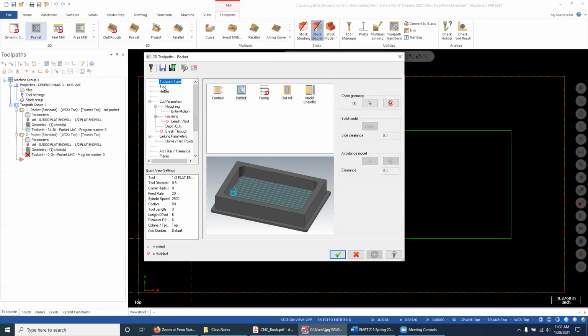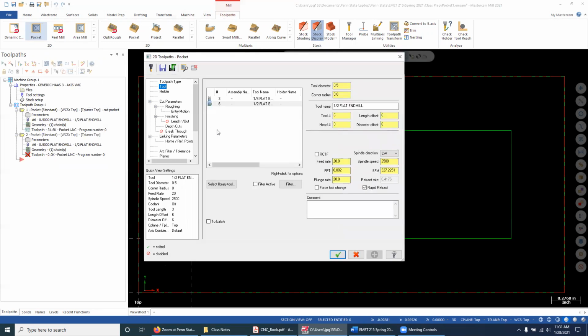So I'm going to choose, in this case, the next size smaller down. So my initial, you can consider this my roughing pocket. In this more finishing pocket, what I'm trying to do is to take out those corners a little better without using the 1/4 inch flat end mill the entire time. And so hopefully, be able to save myself a few minutes of machining time, but still get closer to where I want to be in terms of doing an example of rounding out those corners a little closer to the actual sharp corner that's left from the geometry.